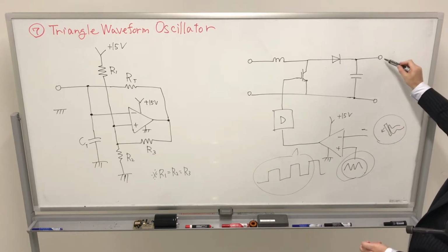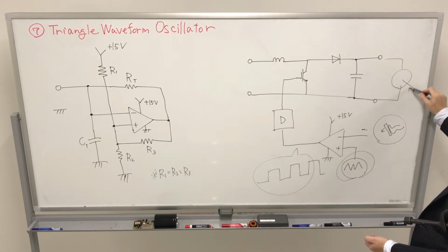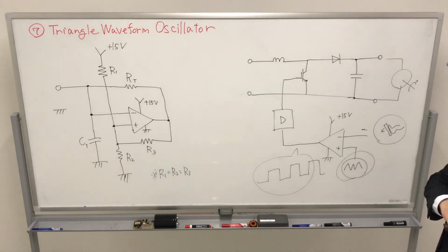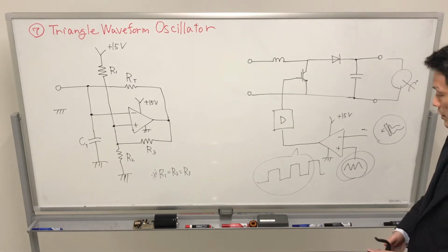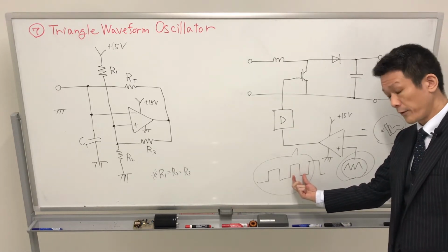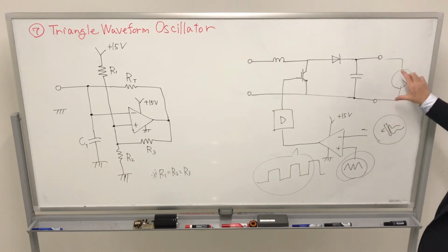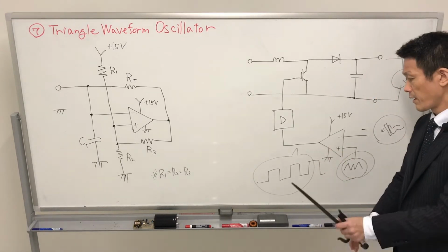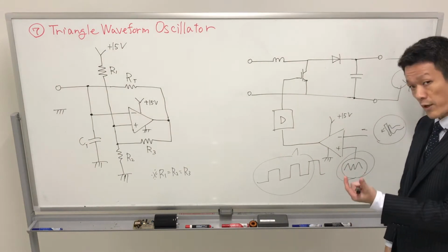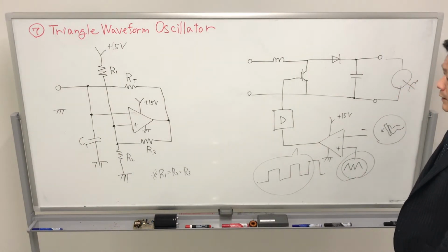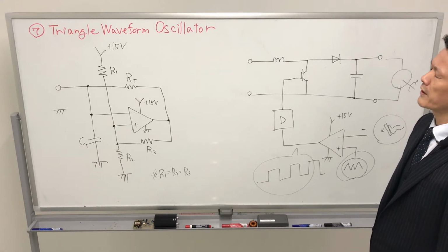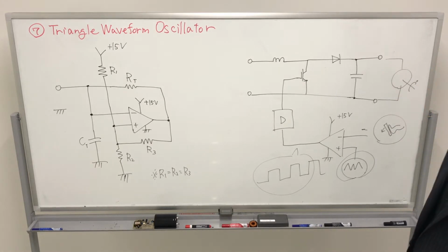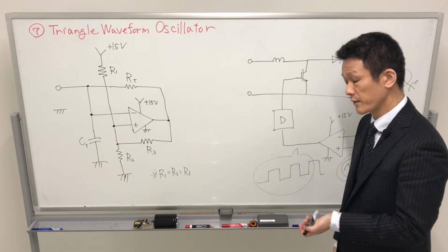The output voltage is connected to the DC motor, and we can control the speed by the acceleration. So we call changing the pulse width, which gives us a variable output voltage, PWM, pulse width modulation control. We discussed this in detail in the fourth lecture, so please check it later.